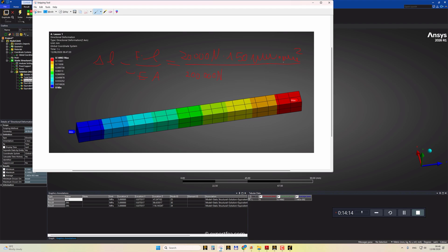So this is the Young modulus, multiplied with the area, which we already know is 100 square millimeters. Let's reduce what we can, Newton and square millimeters. And if possible, let's also get rid of 4 zeros from here, 4 zeros from here.